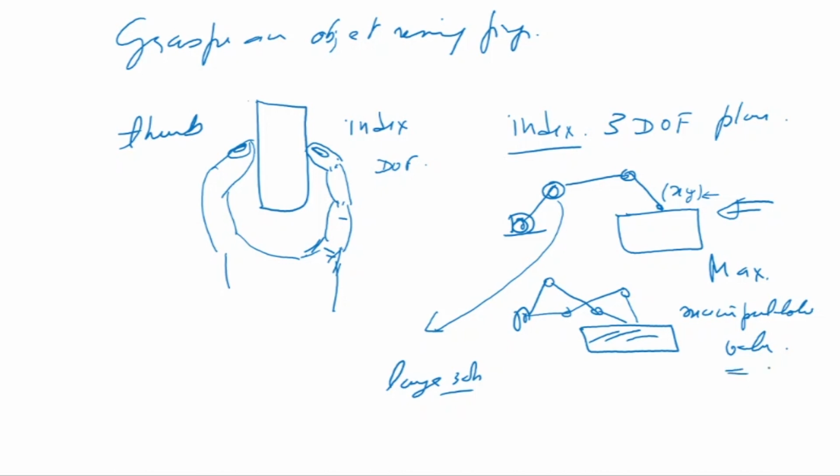And when we follow a motion in space, when you're moving your fingers, what you're doing is following the gradient of dw by d theta. Okay, this is what our k1 is. So it has been proved that when human beings move our fingers, we move our arms, we are always moving such that our manipulation ability is being maximized, and we are following the gradient of this, because of which the manipulation ability is being maximized.